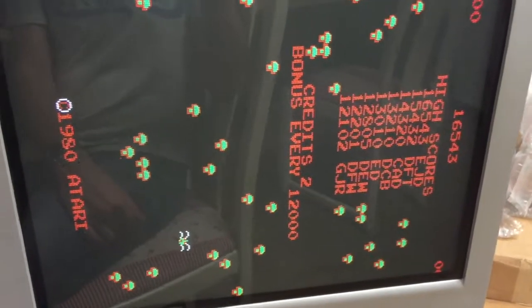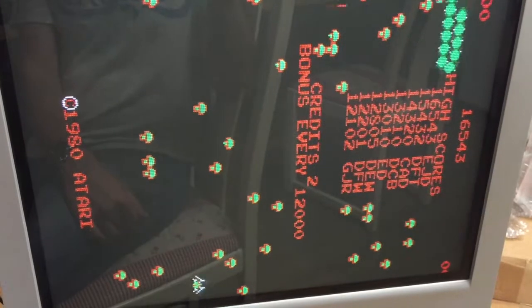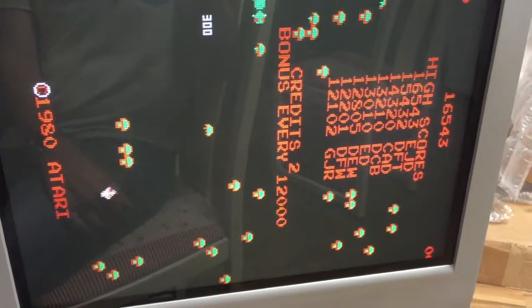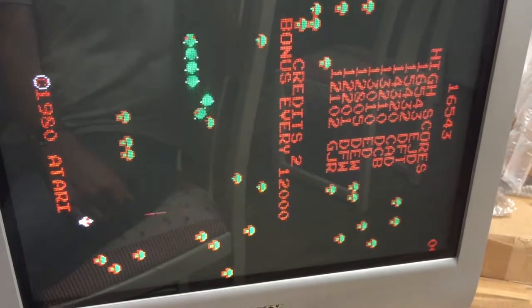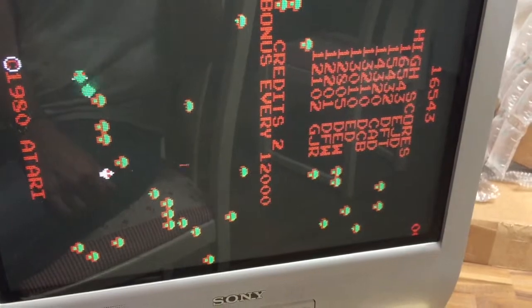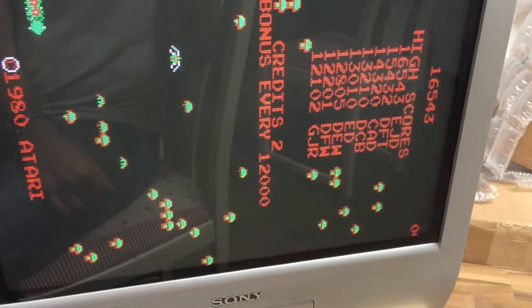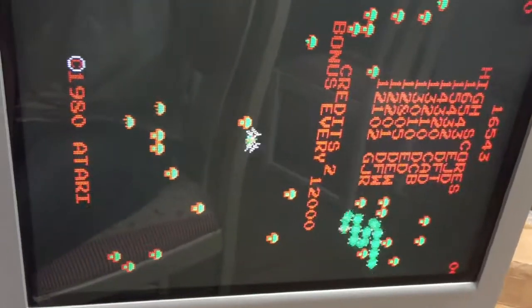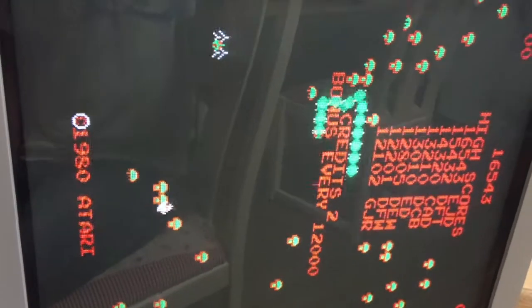So the basic rule that I wanted to show you: if you have the complete loss of a function, always look at the beginning and the end of a circuit first, because those are the likely spots where the problem should be originating from. Actually it turned out to be working for this example, which makes me quite happy. So the point of the video is actually safe.